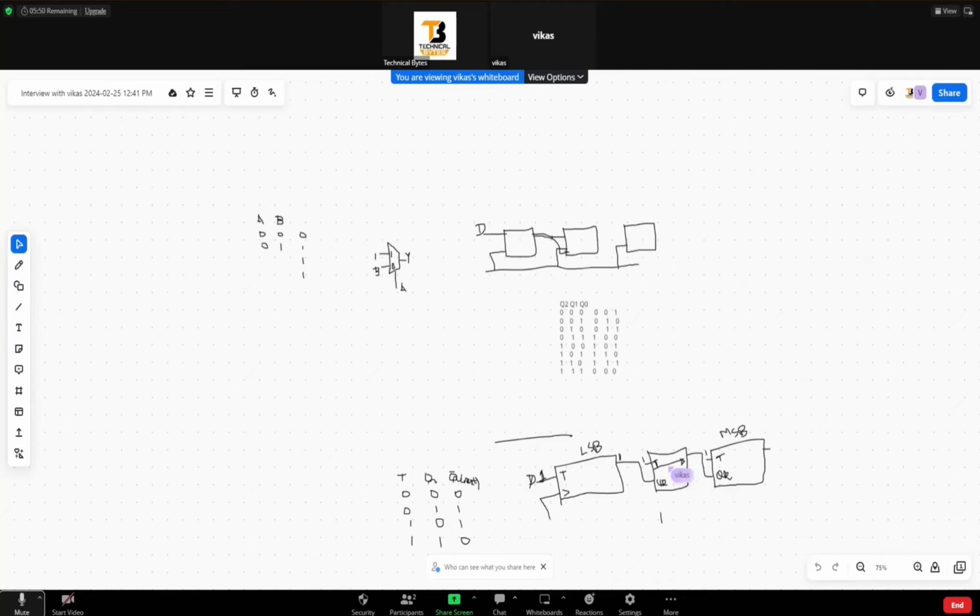You are saying this for the second flip flop and third flip flop, this clock will be coming in the same cycle. Same cycle meaning what? When you say the same cycle, the positive edge will be seen at the same time, and both will become 1 1. No, sir, I thought we will get 0 1 0 only next time, and then only 0 1 1, because there will be delay in this flop.